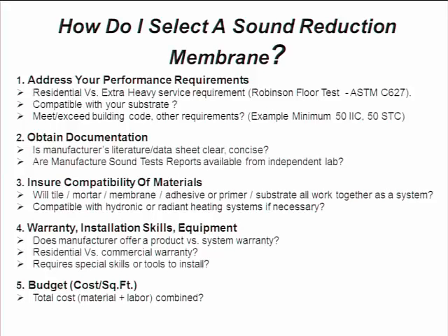Another important step is to ask what your manufacturer's warranty is. Does his warranty relate to just the membrane? Does it relate to the membrane and the bond, or does it relate to the entire system where you're looking at bonding to the substrate and then bonding to the membrane with the tile? And how is that spelled out?